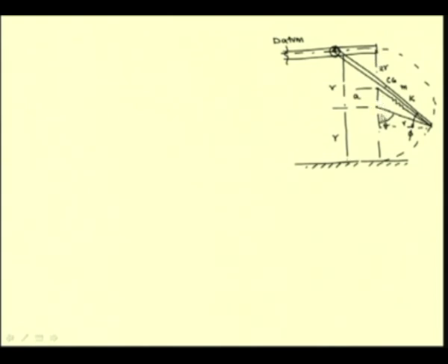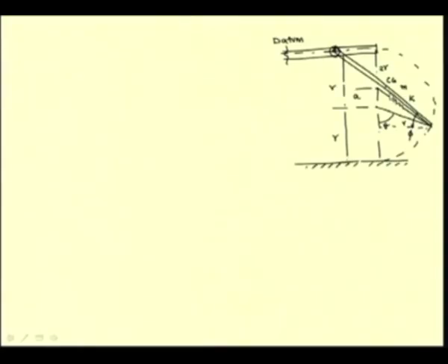So we are interested to know that when this theta is equal to 0, or for this door in the completely closed position, the door is having a stable equilibrium. So let us fix this as our datum, that is the top slot in which this roller slides as our datum, and measure the CG of this door with respect to the datum.